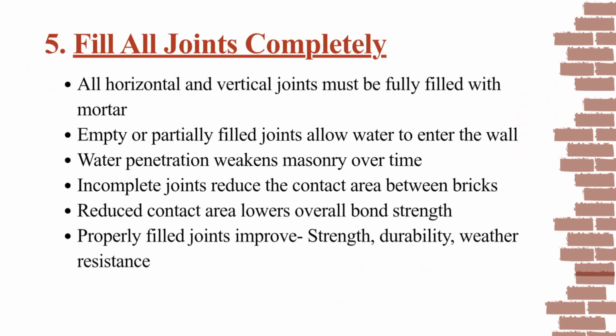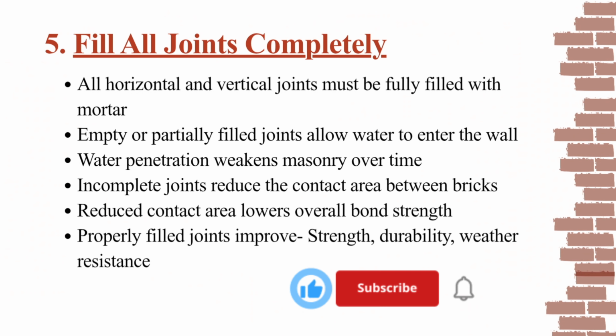Incomplete joints also reduce the effective contact area between the bricks, lowering bond strength. Properly filled joints improve durability, strength, and weather resistance. So, filling all the joints completely and properly is the most important point in brick masonry.